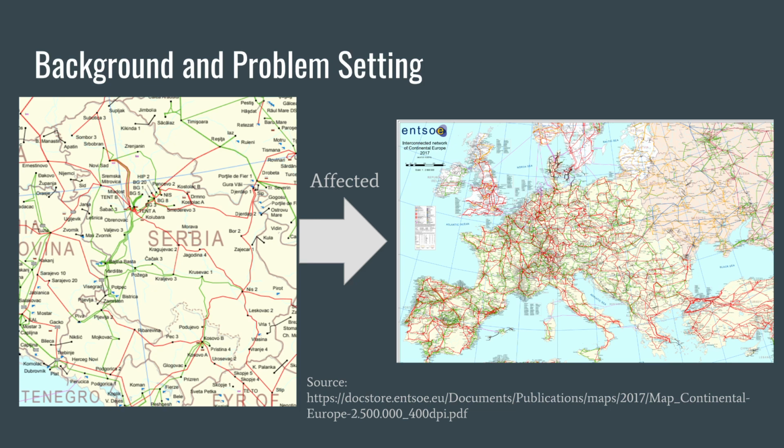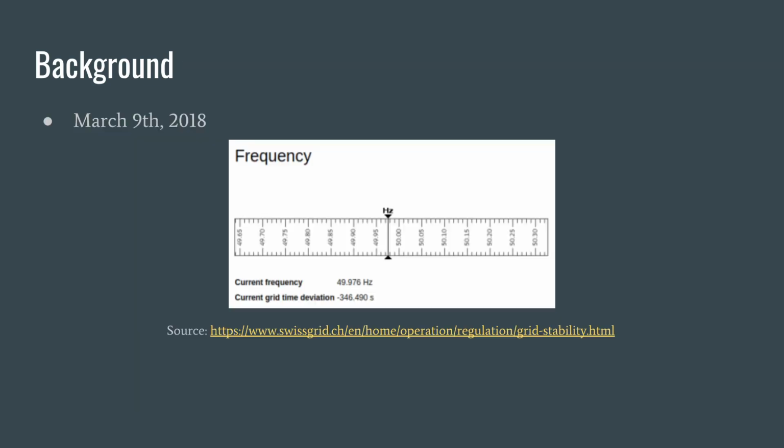This net generation shortage continued for months, with the European grid's average frequency being below its nominal frequency of 50 Hz. Over time, this frequency error caused clocks that derive their time from the frequency of the mains power grid to run slow. After months of frequency error, mains clocks ran as much as 6 minutes slow, causing real issues for affected people and industries. This case demonstrates the importance of controlling the power grid's frequency by proper feedback control of its generation plants.